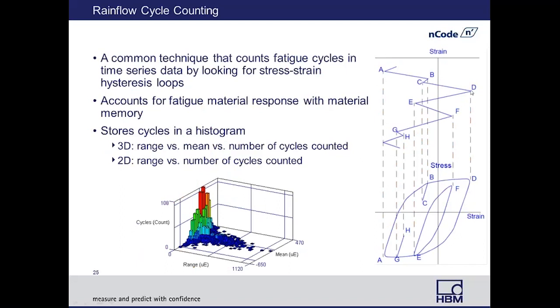And what we've then done is we've projected those strains down onto a plot below, which is showing us stress versus strain. So if you think about it, if we have at point A a fairly low strain level, it could be tensile, we can plot that here, where we also have the corresponding stress with that. So here's stress magnitude, and then here's strain on the horizontal. As we begin to increase our strain, we can go up to B, and in this case that does go through the yield point.